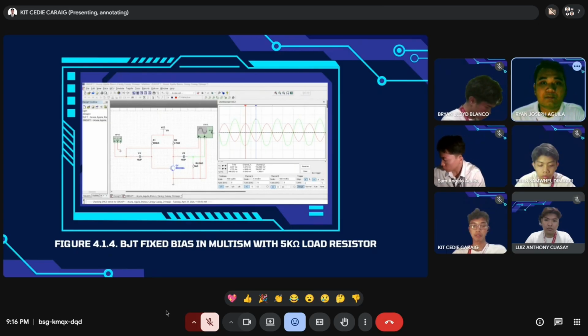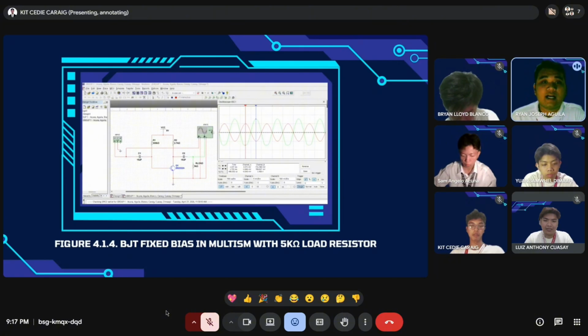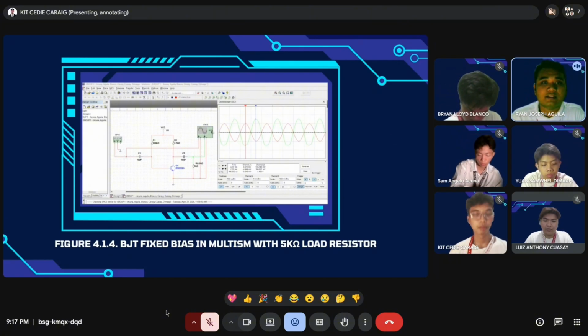The input is approximately 4.98 millivolts, and the output reaches about 1.82 volts on the oscilloscope, for a gain of roughly 365. For the hand-solved value in Table 12, using an input of 4.97 millivolts and an output of 768.83 millivolts, we compute 768.83 millivolts divided by 4.97 millivolts, which equals a voltage gain of 154.69. With a 5 kilo ohm load, the circuit experiences minimal loading effect, and the amplified signal is largely preserved at the output. This represents the highest gain among the 5 configurations tested.